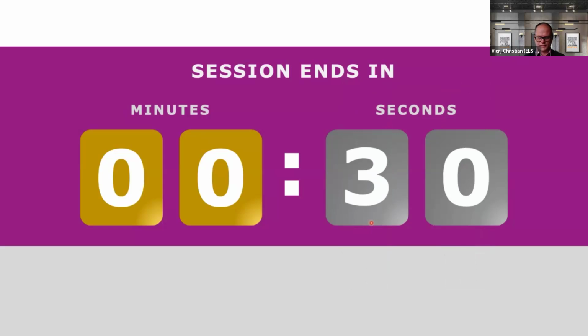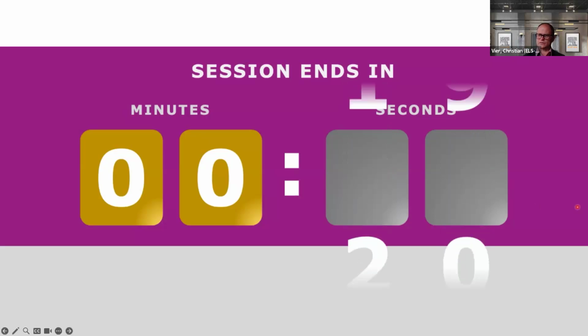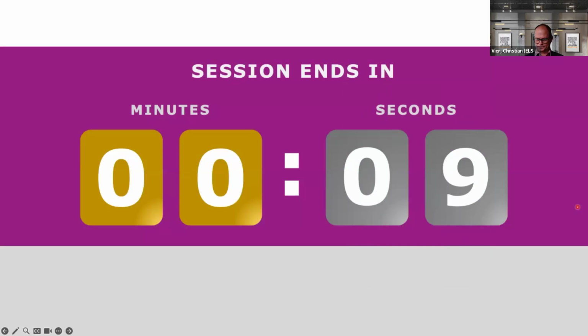So we still have 30 seconds left. Take the link from the chat box, change the units to degree Fahrenheit and to PSI, add the point at 130 degree Fahrenheit, and let me know what the vapor pressure in PSI is. 5 seconds left.